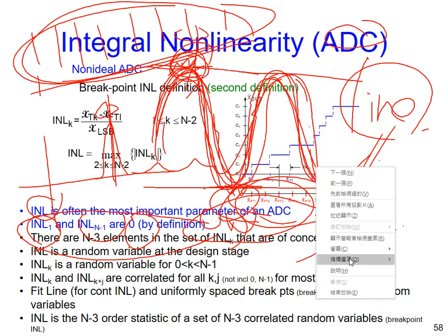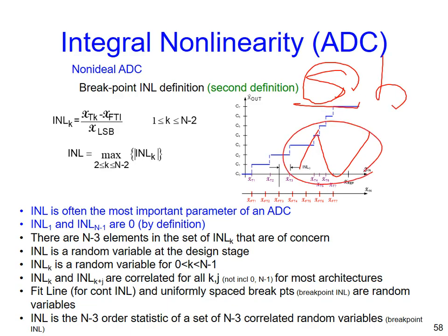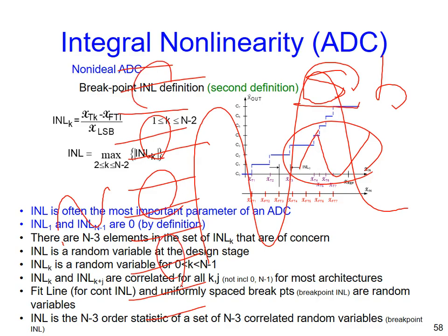Why? Because for your SNR, signal to noise ratio, you say, hey, look, I reduced my signal. How about the quantization noise? Exactly the same. What is quantization noise? You have so many quantization levels, right? If you have your signal here, or you have your signal there, if it is ideal, the quantization error is the same, right? Understand? The same condition here, here, over there. So never mind what range you would like to apply for your input, this is exactly the same in the ideal case.